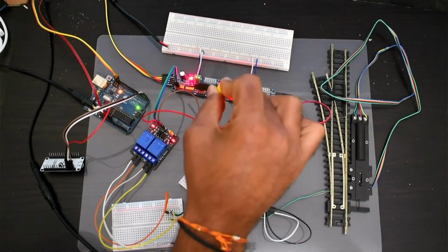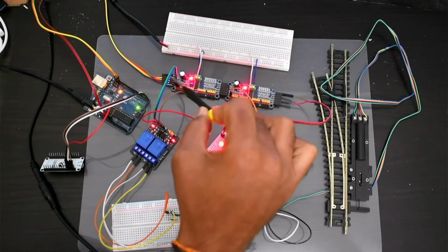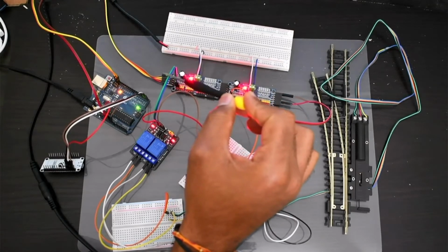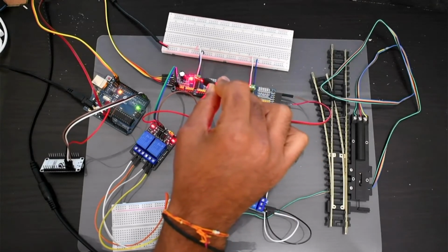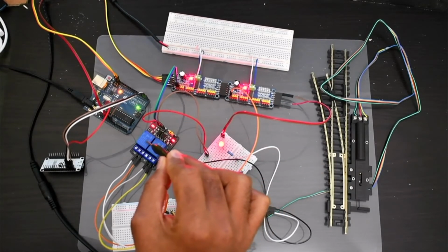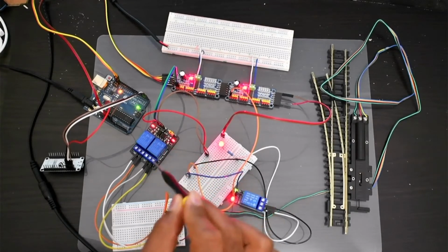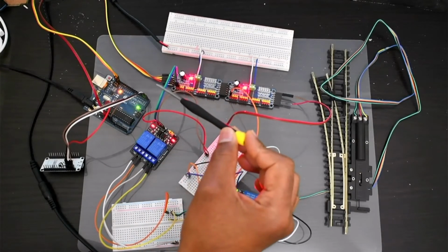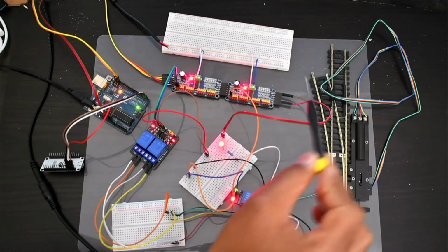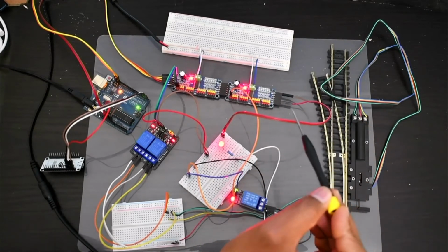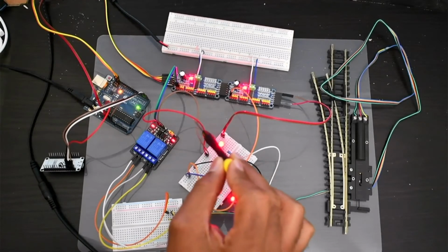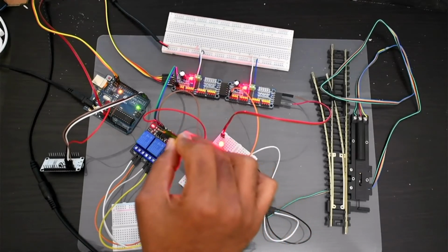and the rest is the same as how we configured the snap turnout earlier. From board number 1, pins 0 and 1 are coming, based on the address which our application will tell us. It has told board number 0, pin number 0 and 1, going to the snap turnout relay switch. So these two are the signals from the PCA9685 board for the snap turnout. And here you can see, from the end of the board I have taken 5 volt and GND which is coming to this breadboard, and from that I have used the same 5 volt and GND from this breadboard to power up this relay switch.